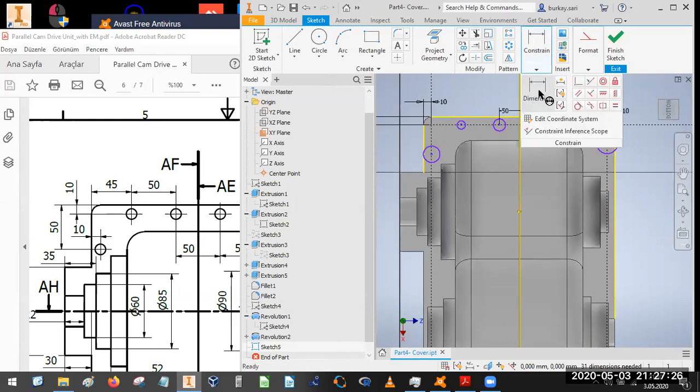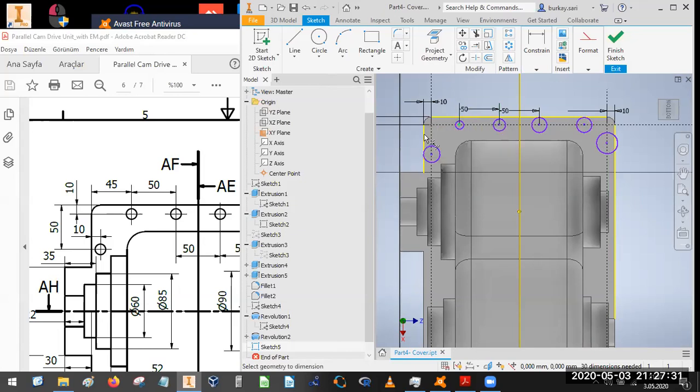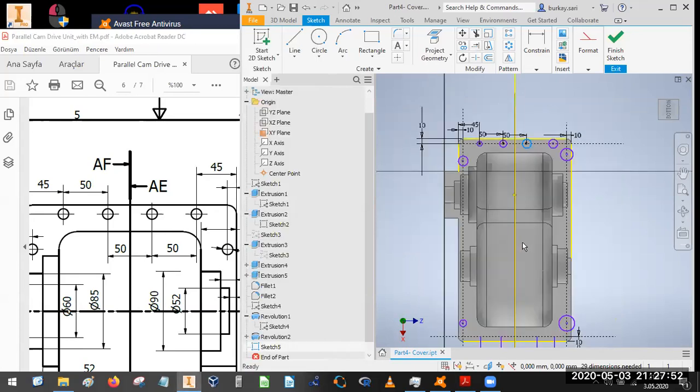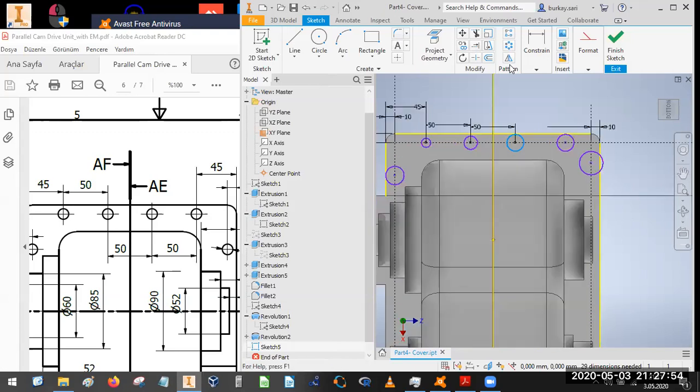We also have the dimension from this point to this point, which is 50, and when I just create this one, then I have defined one dimension here. For example, the figure here has all the dimensions mentioned, but when I use circles instead of lines, I have to define their diameters. I would like to make equal their diameters to each other.